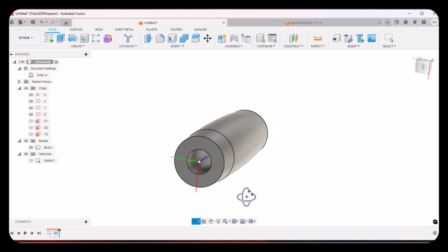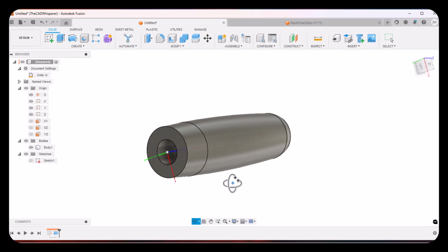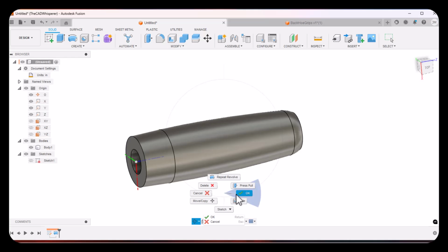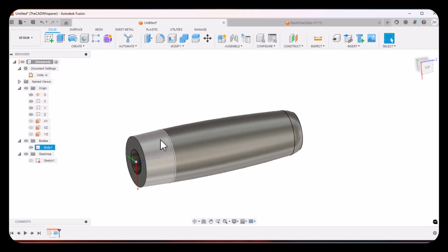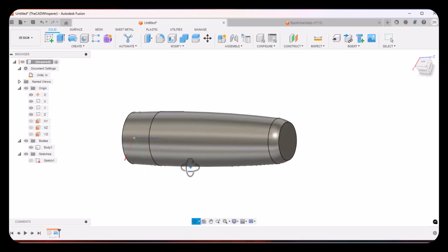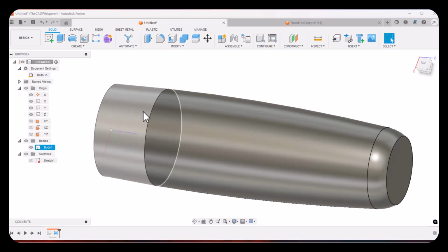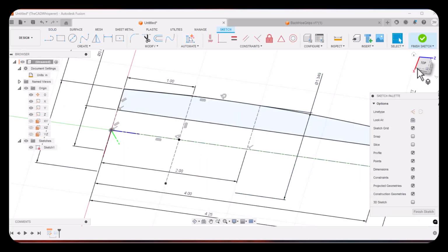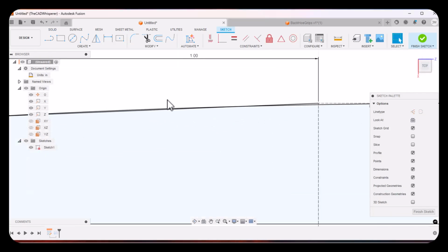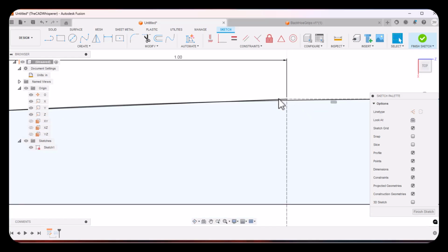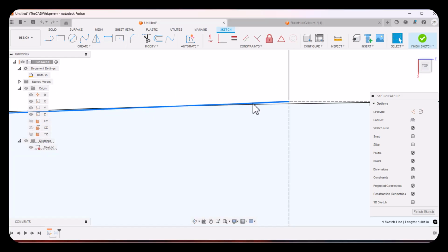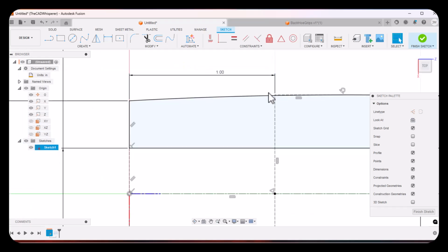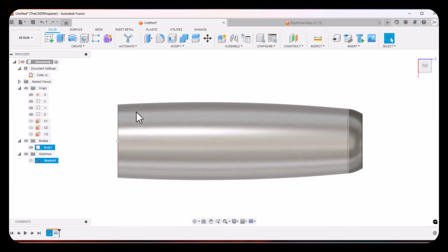And so here is the geometry before we cut any slots into the solid body. I want to offset this down, and I'm a little bit concerned about what this line is right here. So I tried to investigate why this circle between these two faces existed. So I'll go back to my sketch and edit it, and I'm going to zoom in here. When I was creating this dimension, I accidentally put a line in here, so let's delete that line, and then we'll finish this. And so that's what it was. I made a little mistake in here.